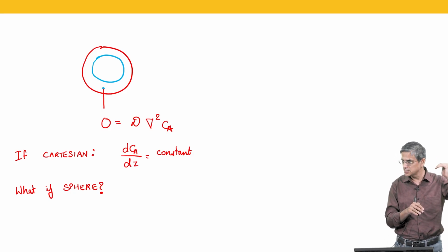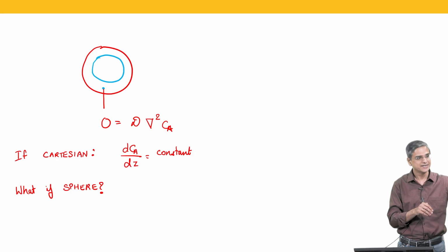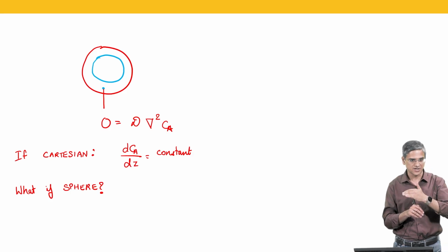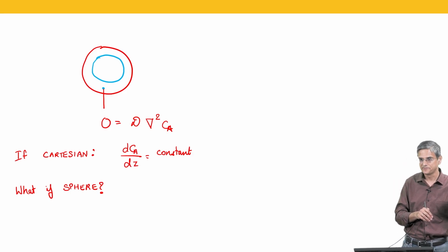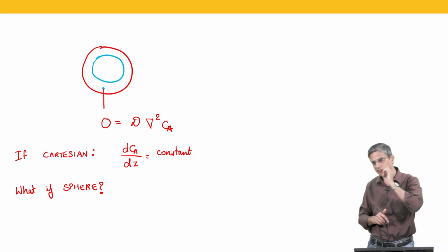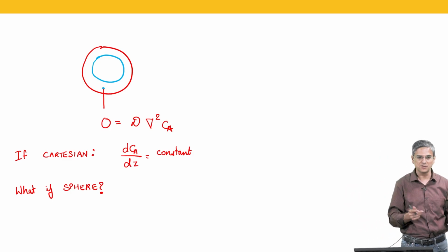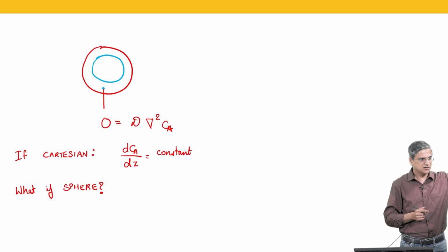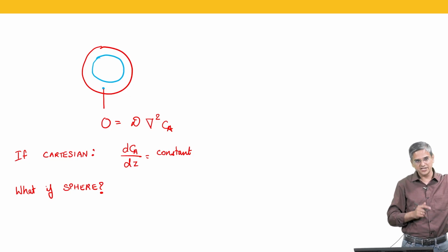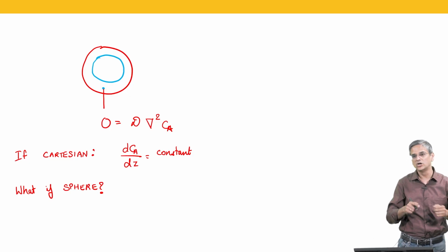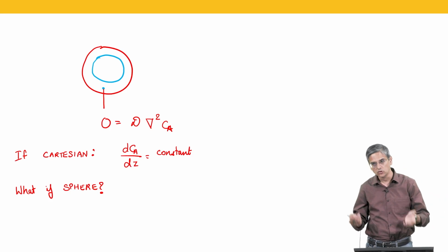Fluxes are not matched, that is what I talked about 10 minutes back. It is the total flow that is matched, that is flux multiplied by area. Okay. What Fogler's book or Levenspiel's book or Schmidt's book does, it takes shell balances and says that flux multiplied by area through the red is equal to flux multiplied by area through the blue.